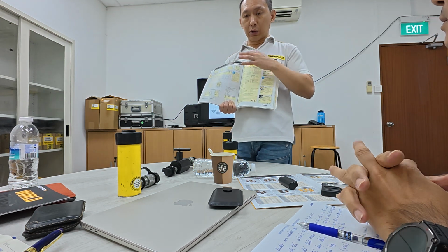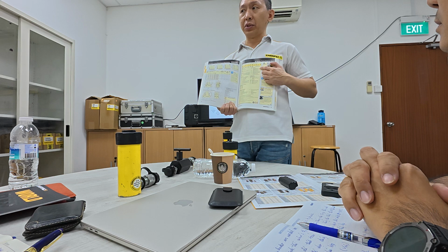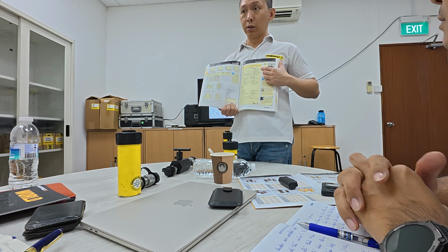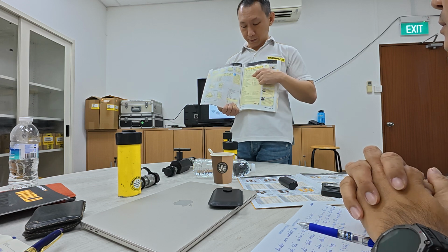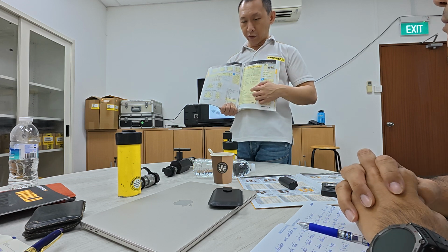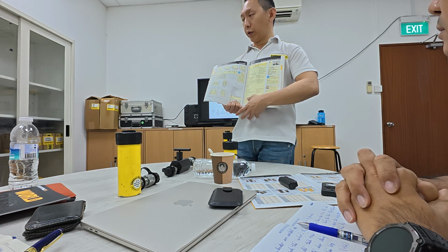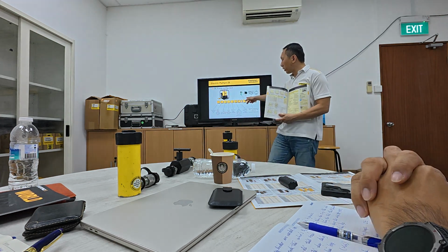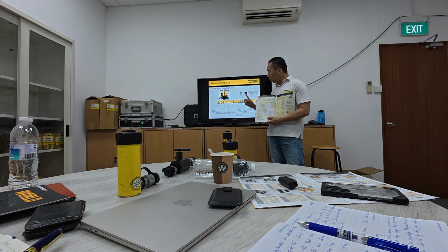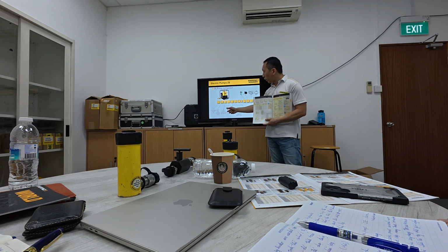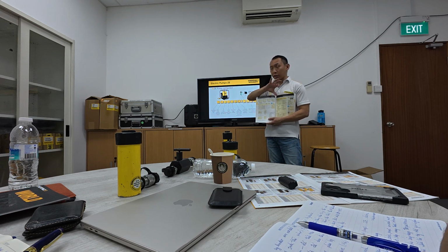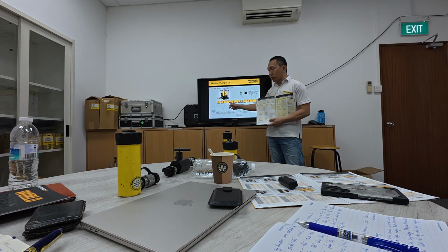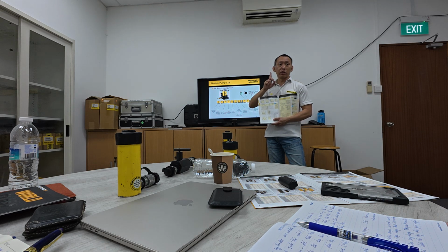To size this, it's actually always dependent on the application, because different applications call for different types of valves and different options as well. So if you look at this configurator, what I need you to know is this one is dependent on the flow group, for what type of application, the type of flow. The valve type will depend on the type of cylinder and the type of application.